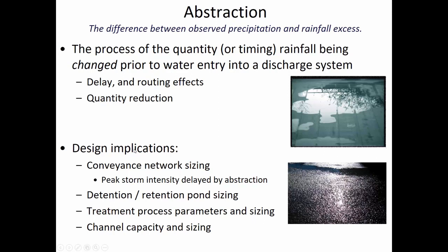During a 5 or a 10-year storm, the abstraction is just going to be a small part of that. But during smaller storms, you may not even have enough rainfall to satisfy the abstraction. So sometimes if it's just sprinkling rain out, we talk about how bad the drainage is here in Huntington and how Fifth Avenue fills up with water and it's kind of like driving through a river. But on a day where it's just sprinkling rain, there isn't any water going through the gutters and there's no flow to the pipes because it didn't even get the concrete all the way wet. And so you can get a feel that there's a certain threshold of water that doesn't generate any peak flow. There's no runoff until the abstraction is satisfied.